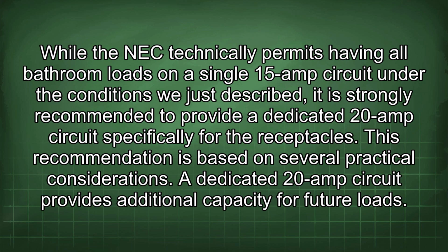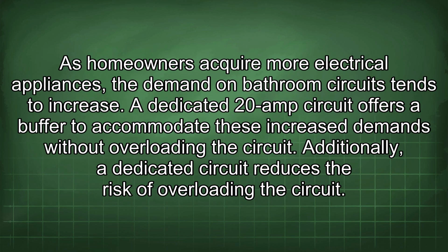This recommendation is based on several practical considerations. A dedicated 20 amp circuit provides additional capacity for future loads. As homeowners acquire more electrical appliances, the demand on bathroom circuits tends to increase. A dedicated 20 amp circuit offers a buffer to accommodate these increased demands without overloading the circuit.